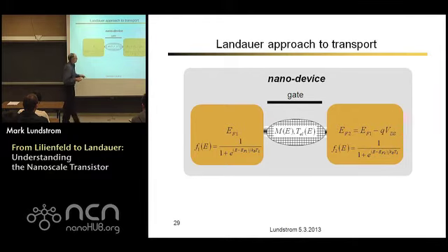It's heavily doped, but it might have a different Fermi level, or we'd say different quasi-Fermi level. And then we have our little device inside. This is our nano MOSFET. And we're going to characterize that device not with a mobility, because mobility really doesn't make sense at this length scale. We're going to characterize it by two parameters. One is the number of channels for current to flow, and another is the transmission.